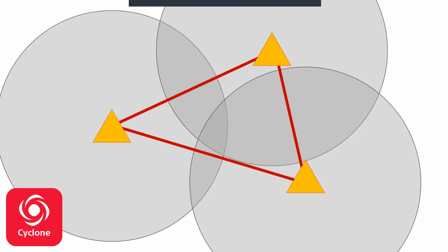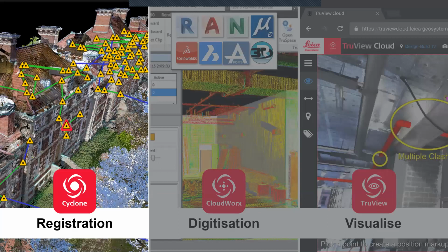For buildings with hundreds of floors and more than 80, 90, or 100 rooms on each floor, to collectively make that whole building plan in a single stage, we need Cyclone software, which allows you to register the data. You can see this on your left hand side. It merges the data from different scan positions and from different scanner sensors, whether of any other brand or from Leica. So this software is strong enough to handle data from all the different brands existing around us.